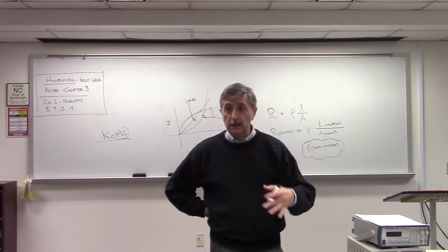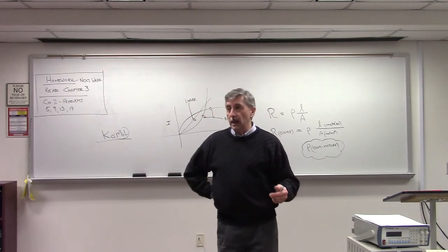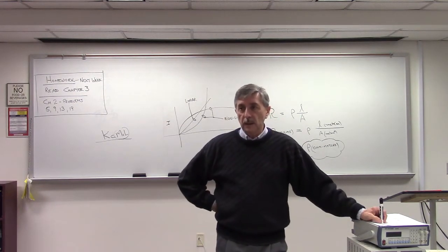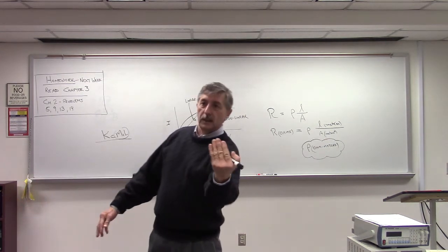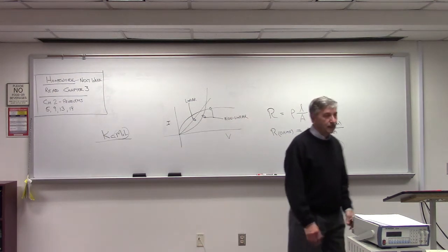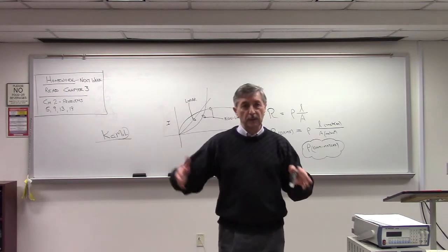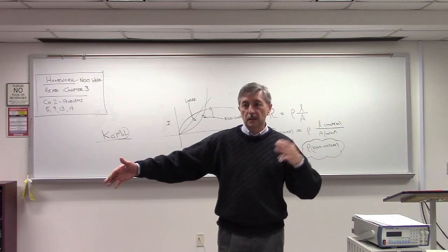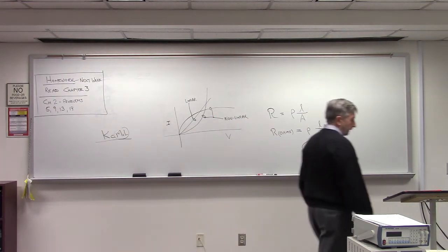Sometimes you have to do stuff like that, and you should know that by law, believe it or not, there is a law that says all wires have to be labeled every 2 feet somewhere. Usually when you want to look at a wire, the labeling is on the back side and you can't see it unless you have a mirror. But by law, that's the situation. Everything about that wire has to be repeated every 2 feet along its length: the type of insulation, the specifications, the wire size, all that good stuff. Okay?